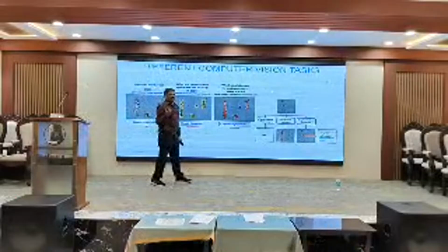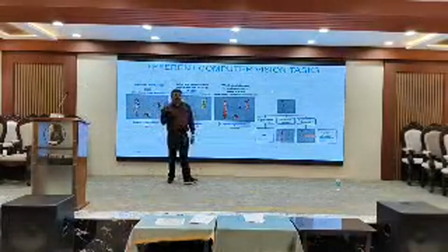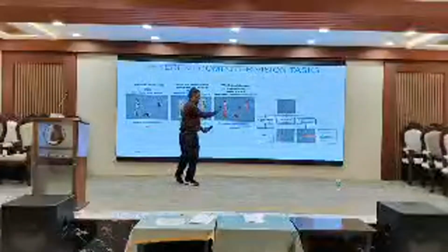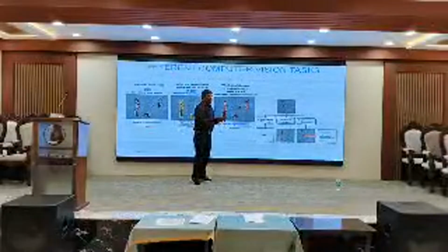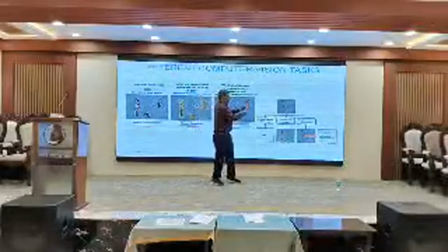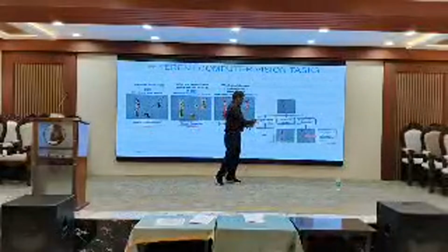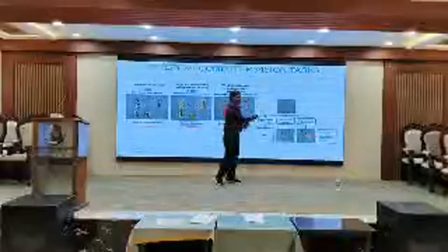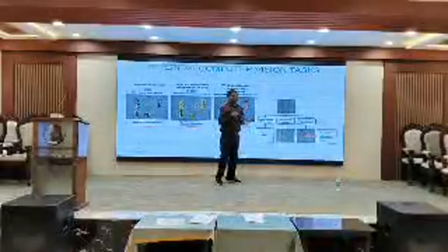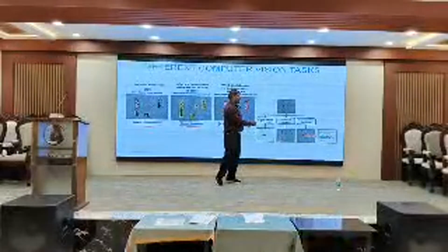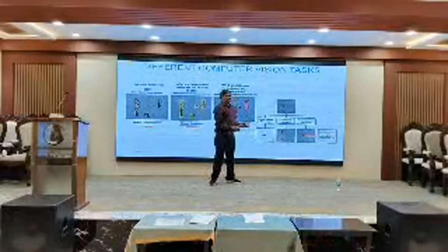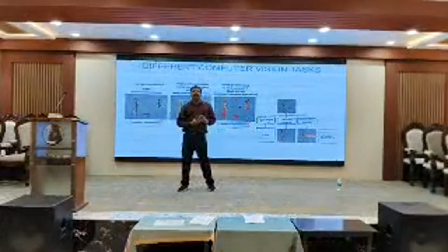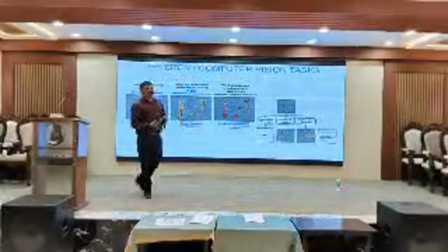So basically, you have an image. We try to use drones. We collect the images and we automate the process and try to tell where in the image there is a crack, then at which location the crack is, and then exactly quantify it pixel-wise. Because quantifying pixel-wise only, they use the geometrical information about it, like length, maximum width, direction, that means orientation of the crack, so that they know how far it will propagate and fail. So that is the basic classification.